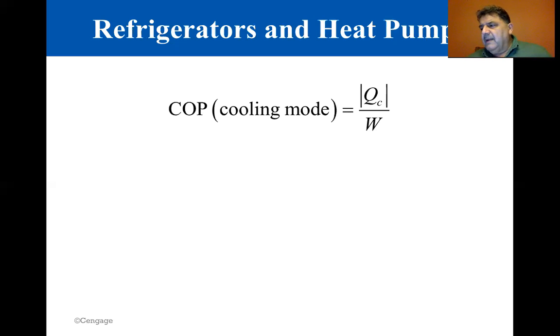A heat pump operating in heating mode warms the inside of a house in winter by extracting energy from the colder outdoor air. This statement may seem paradoxical, but recall that this process is equivalent to a refrigerator removing energy from its interior and ejecting it into the kitchen. The coefficient of performance of a heat pump operating in the heating mode is the magnitude of the energy rejected to the hot reservoir divided by the work done by the pump.